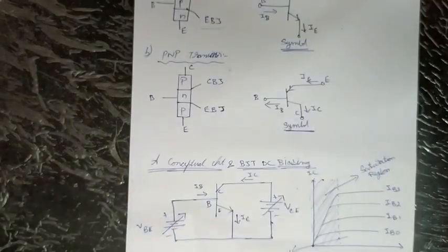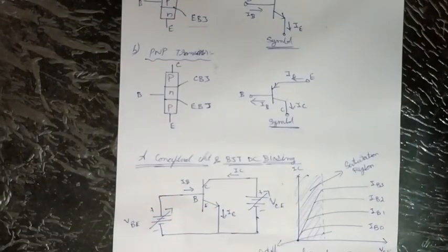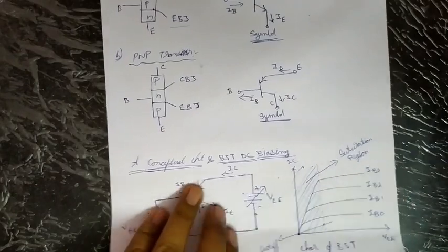of transistors and BJT DC biasing. To obtain a single transistor characteristic curve, plotted for the characteristics of BJT in the IC versus VCE plane with IB as a parameter, the DC source is set to a voltage, and then the VCE voltage source setting is theoretically varied from 0 to infinity while measuring the corresponding collector current. So here is the characteristic curve for a BJT.